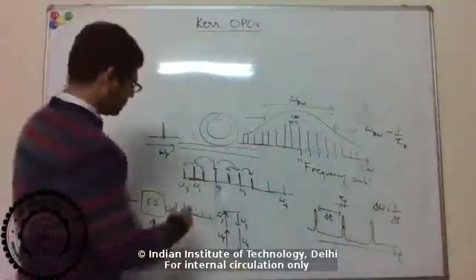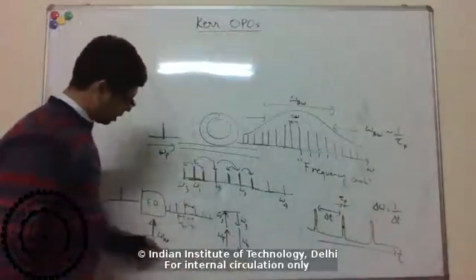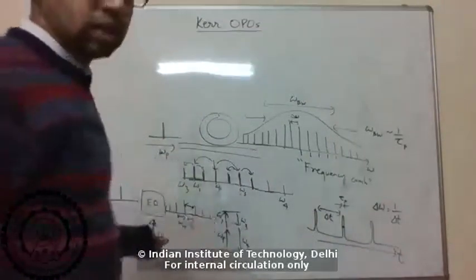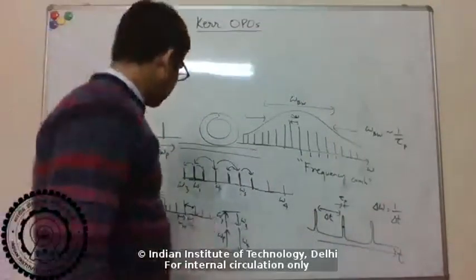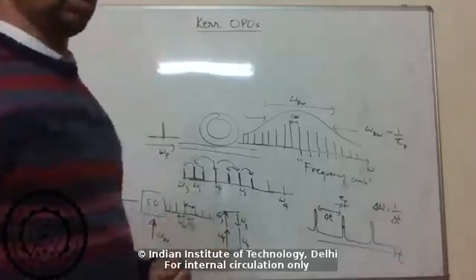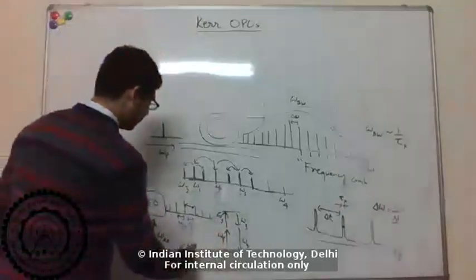Okay. Second limitation is what is the spacing here? That is your RF drive frequency. So that depends on the microwave sources, that RF frequencies, and the electro-optic modulators, which frequencies they can operate. And typically that's less than 100 gigahertz.